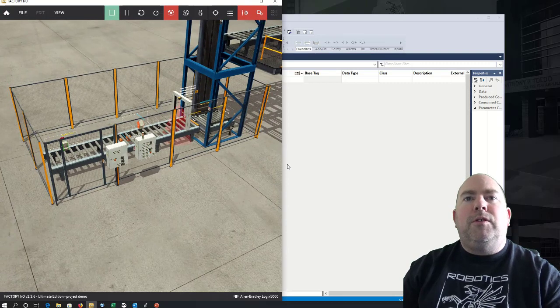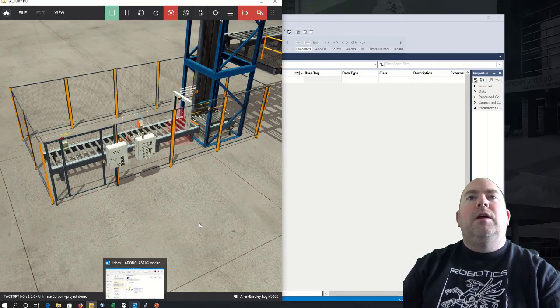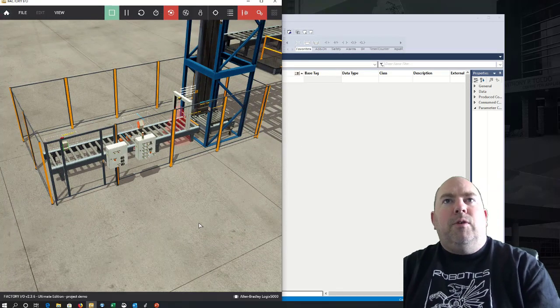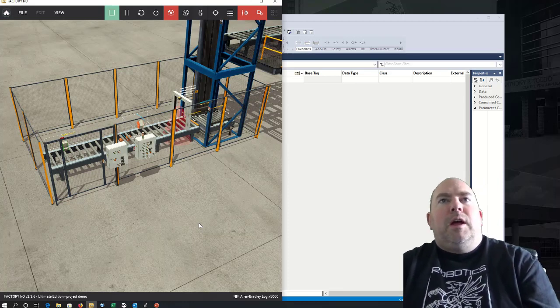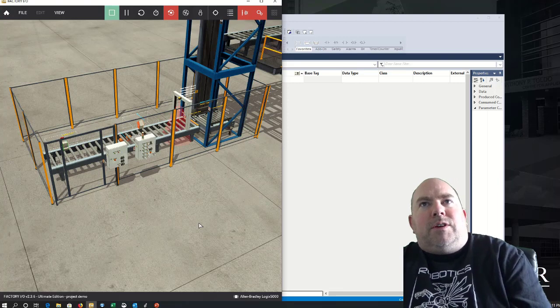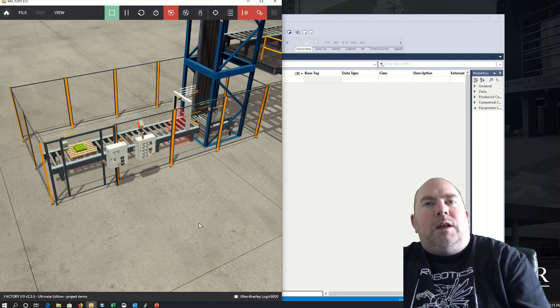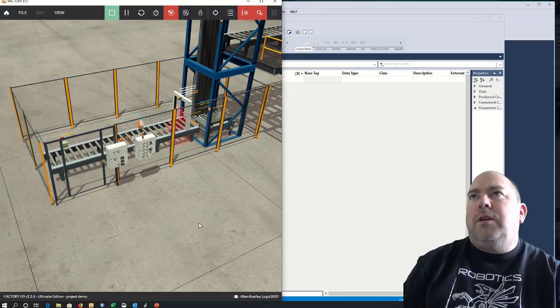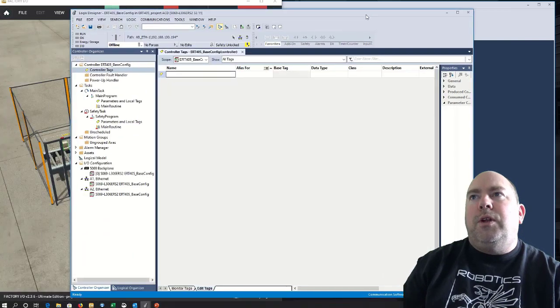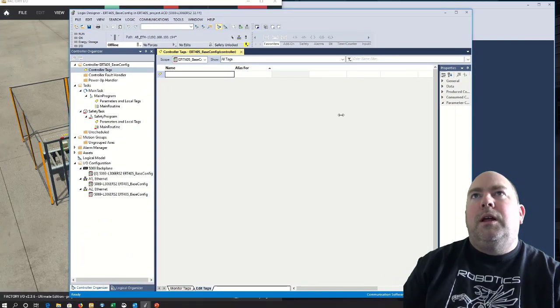So when I copy the safety logic, I have safety logic for one set of contactors. We'll say an e-stop or safety gate is going to shut down everything and just treat it all together. So from that safety program I did before, I'm going to bring the e-stops, gates, and zones and outputs from that.